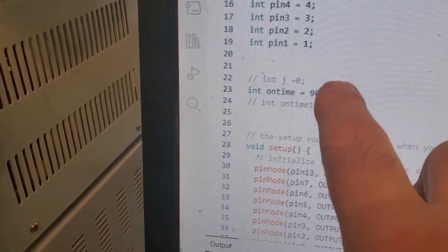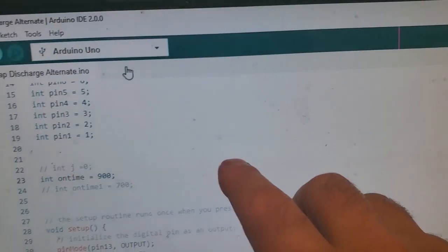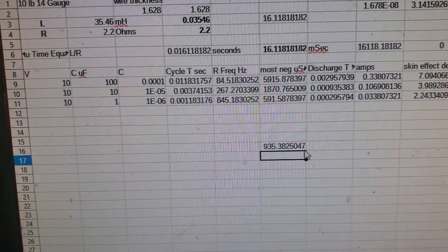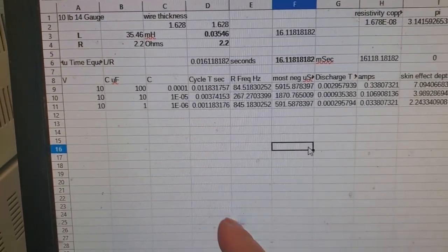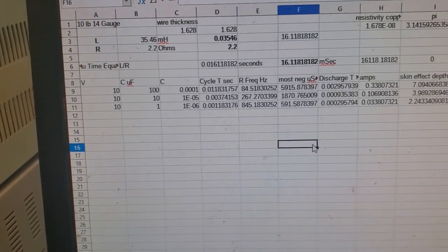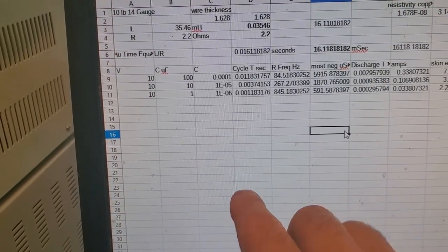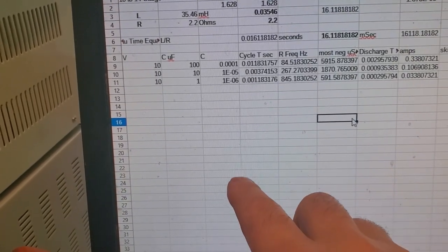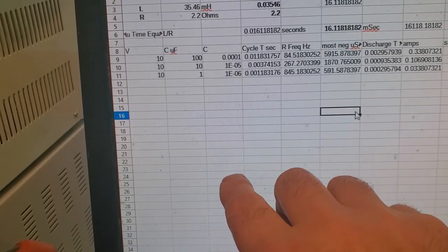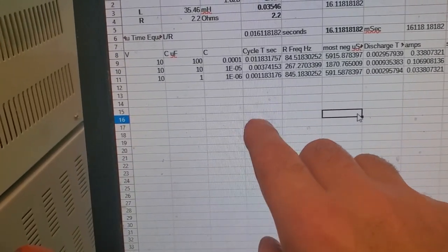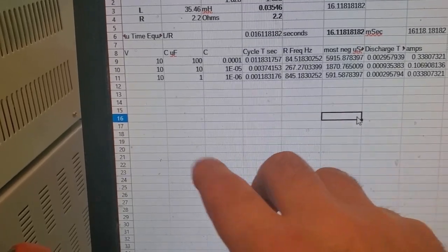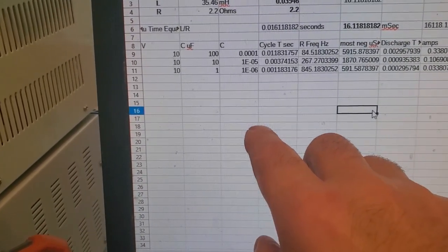But why do I bring up that timing? Because that's where you get the transformation of voltage if you have it set up as a buck boost. And why is that? I don't know why I want to do this on a spreadsheet when I'm just doing it with my finger. But if you think about it, the cap's discharging, and the cap doesn't have some hidden negative voltage, it can continue to discharge. What's happening is the cap's discharging and the coil is charging. And so the cap discharges with the RC constant curve, and then the coil charges with its curve. And when the cap gets to zero, the amp strength in the coil is not going to increase because you're out of amps. So the amp turns would be, I believe, maximal when the cap gets to zero.